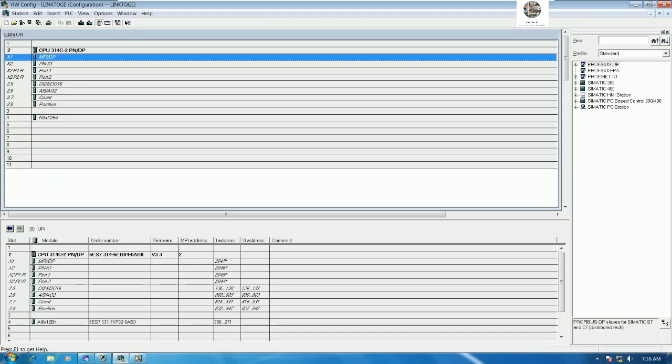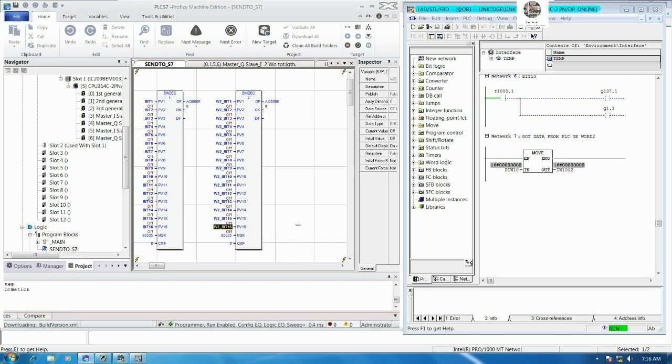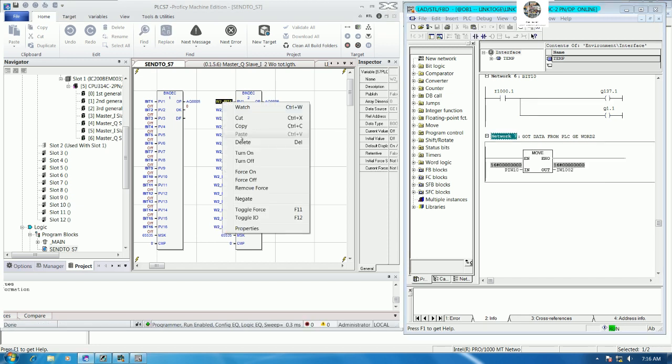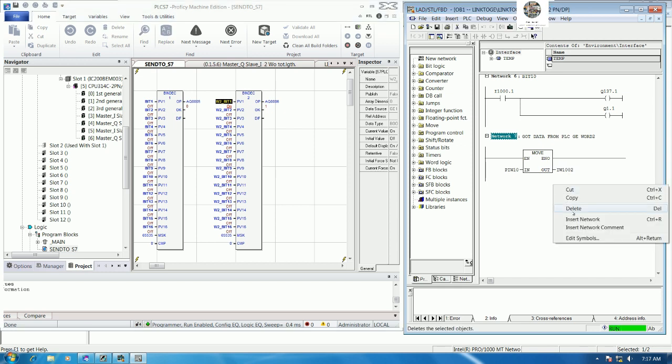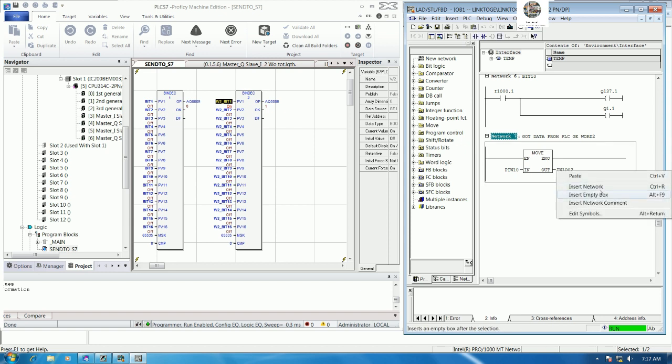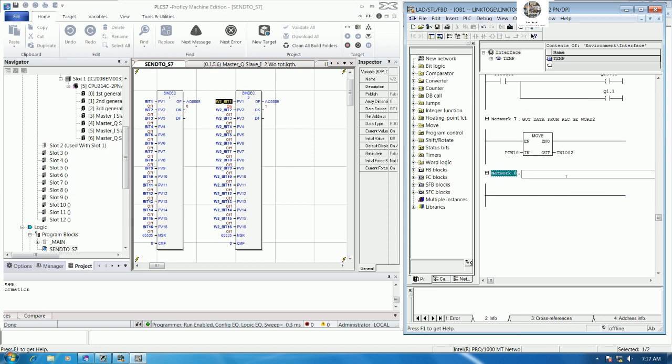And then we can go to PLC GE, and then we can force signal to see the signal. If I turn on, yes, force on, let's see here is 1. So we can convert to bits also, right? Okay, example, I will convert to bit. So word 1, word 2, bit 1, right?